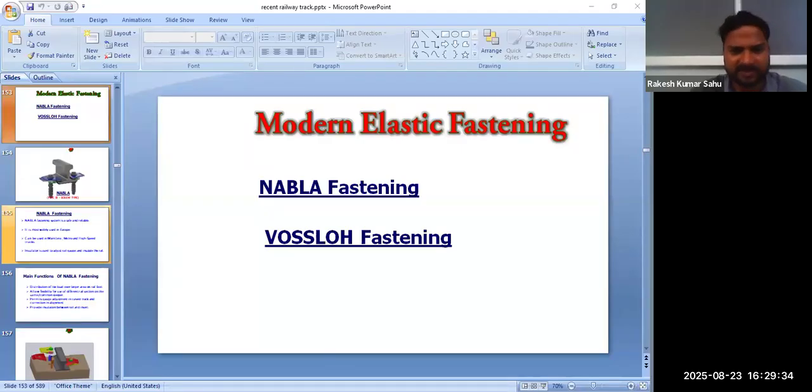On curve, we provide some additional width on the sides, which is clearly mentioned in Indian Railway Schedule of Dimension (IRSOD) about extra clearance on curve. In any case, a minimum shoulder width of 900 shall be ensured on both sides of curve portion of track.